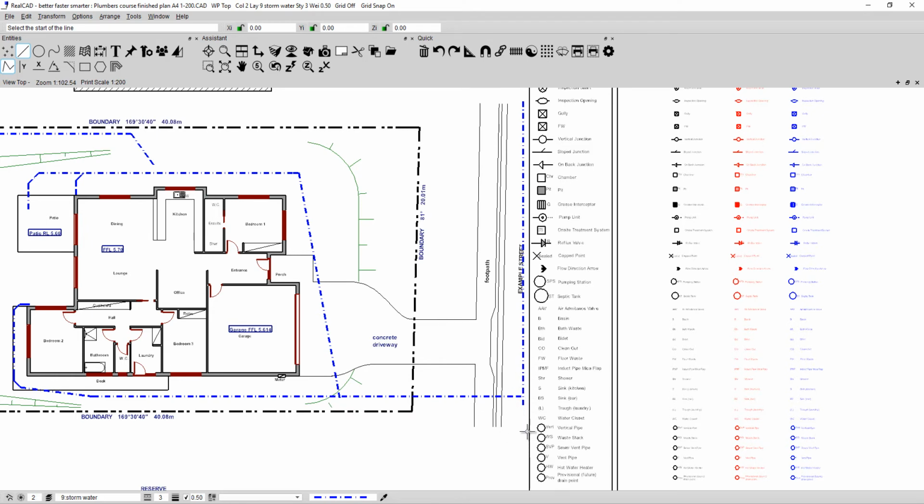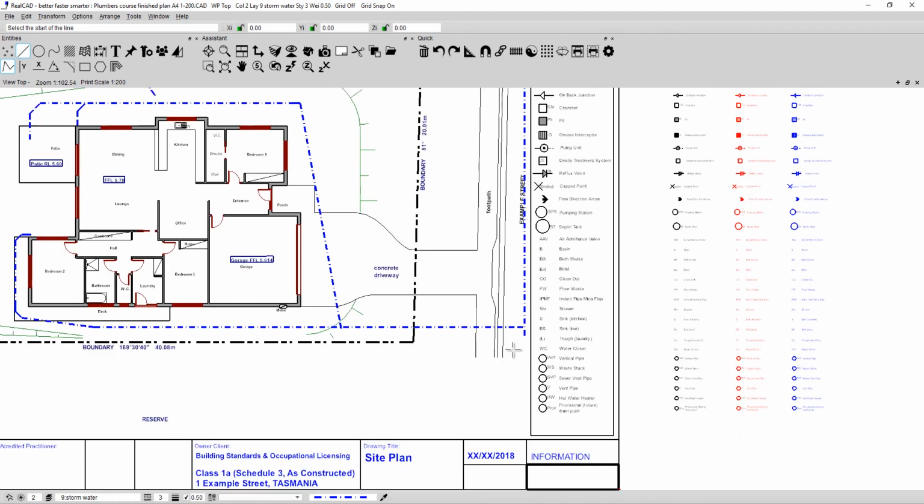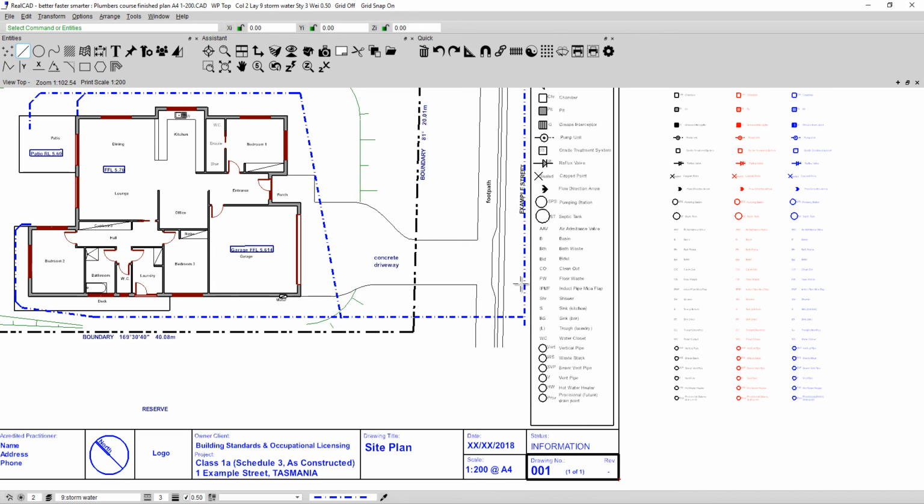This one needs to come down here. It needs to be a bit longer in this direction. So I may as well show you one method of lengthening a line, and that is to select the line, grab hold of its little end point. So I just move my cursor to the end point, click down on my mouse, and I've actually got the line hanging off my cursor here. Okay, and I can again hold down the shift key, just drag it down to where I want it to be, and then let go, and the line will have moved down.